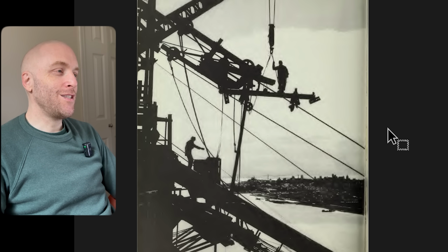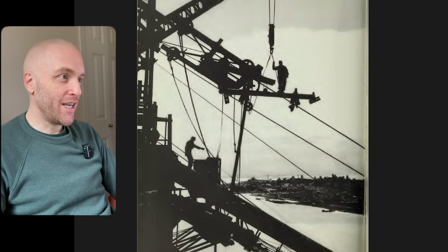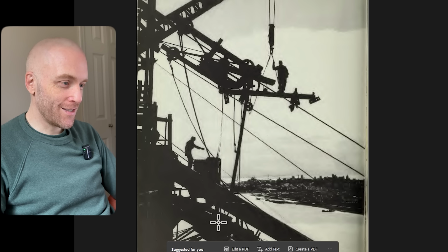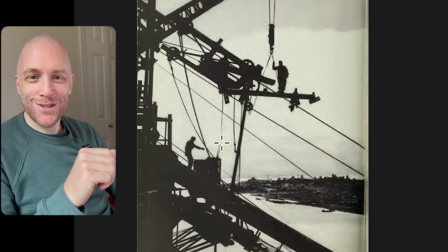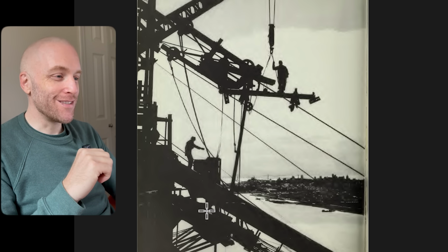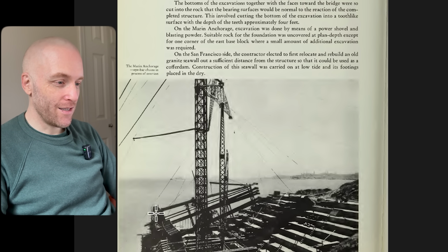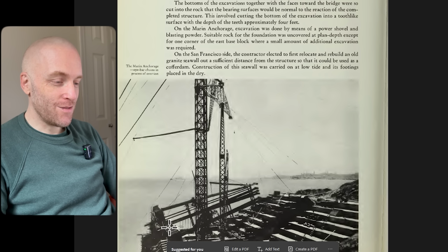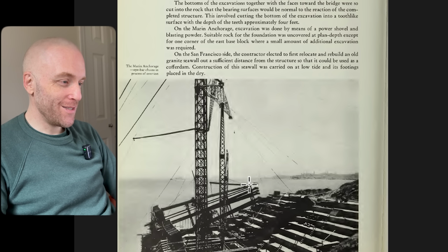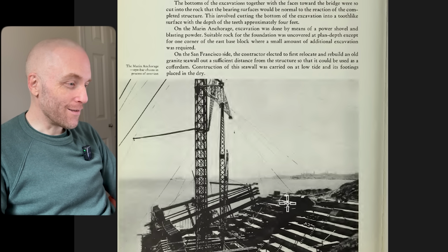You can see in this photo, it looks like a derrick on top of the tower, and then the run up here for the spinning carriages and the adjustment blocks. See, that's all the stuff. Now when you watch a documentary that's black and white, you'll be able to name all this stuff. Here's the start of some of the Anchorage construction. There's a derrick here, a big old tower crane it looks like. Here's the retaining racks back here and some of the I-bars coming in. The keyed foundation blocks, see?